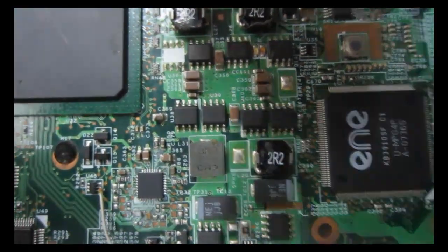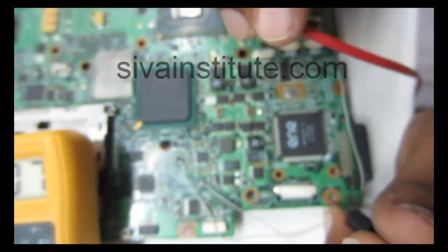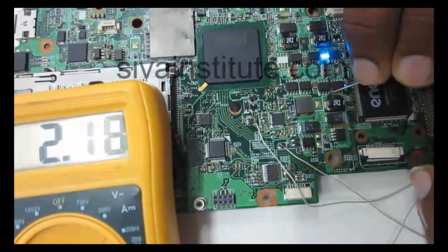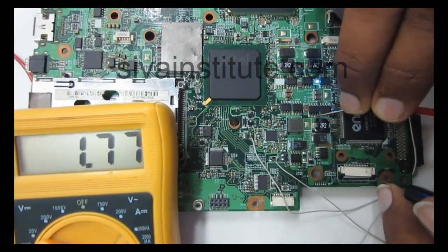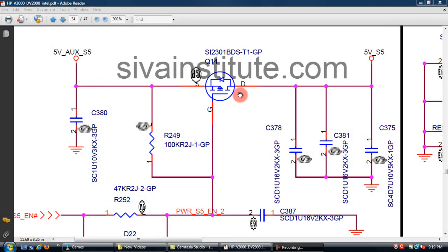We will see without the S5 command at U40 and U39. This is U40 transistor. Gate voltage, U40 gate voltage. Light is on. I will give the S5 command. Light is on. 2.8 volts. 1.9 volts. Okay. This is page number 34.